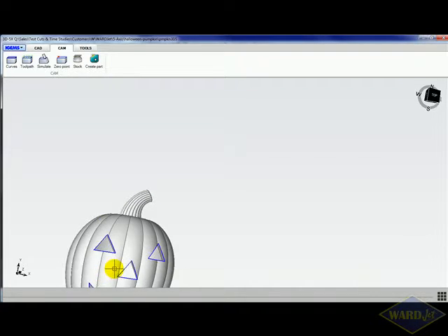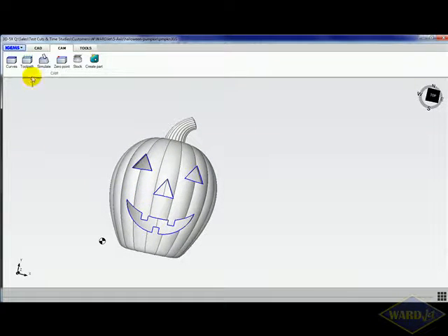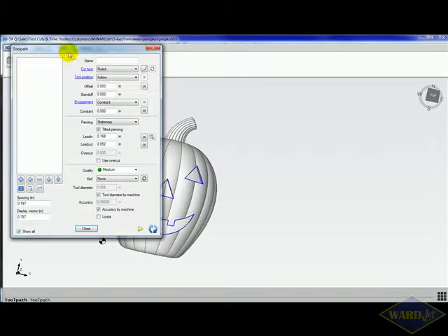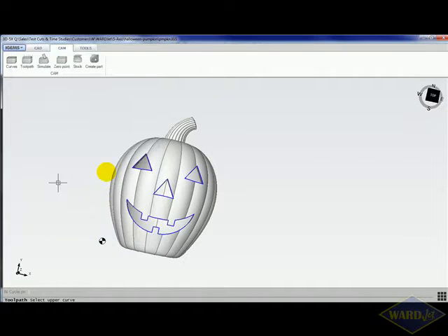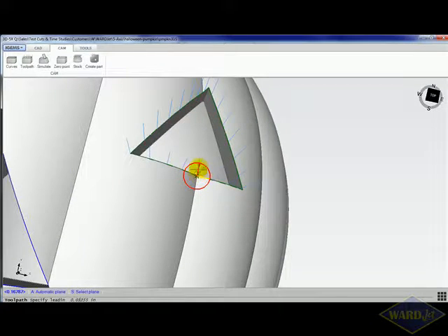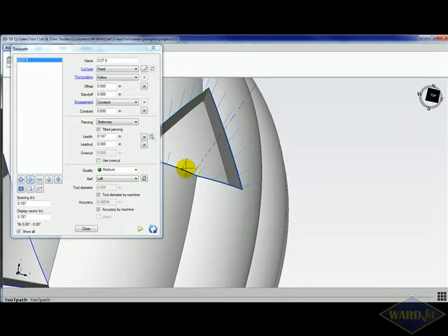So then, nice thing that they've added on the toolpath area, everything's on one page here. Before it was multiple tabs. If we go ahead and add a cut here, I'll pick this curve here and starting points, and we'll go all the way around in direction. Lower curve, I'm just going to hit enter, and then we'll add our lead in and lead out.